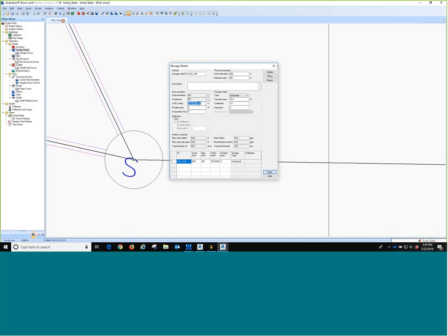I'll go back in here, and I will do the same thing here. Just say it's empty. If my pipe is above that, if my pump, wherever it connects, is above that, I would probably just set it and assume that the invert of wherever the pump input is my water surface elevation. But we'll not worry about that right now, because I've actually set it. I'm going to set the pump input to the bottom of my wet well exactly. Okay, so that looks good.